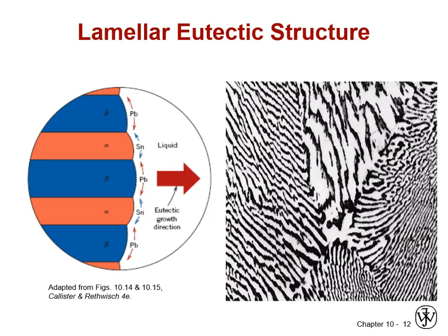They can't stand each other, energetically speaking, and they want to form almost pure components of one another. There's very little solubility of tin in lead or lead in tin. So the minute they solidify, they want to segregate into almost pure phases, a two-phase region.